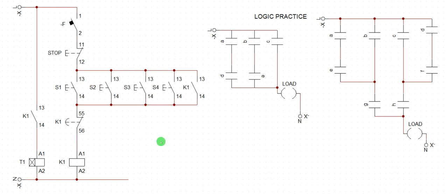Now let's simulate the start station once more. I told you that you can only activate and the machine will deactivate by itself, but peradventure you want to deactivate it, we still have a button here you can use if you so wish. I just gave an example of some methods by which you can design a machine to operate a particular sequence, using the logic of a start station to achieve that particular function. All right, so let's do that now. Let's simulate. Just watch this particular equipment close upon activating any of these.